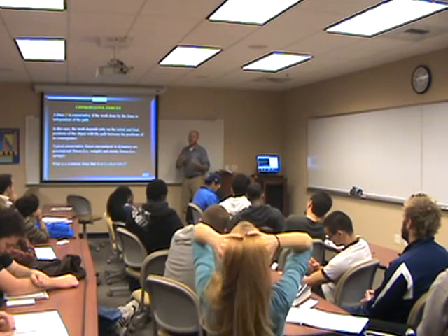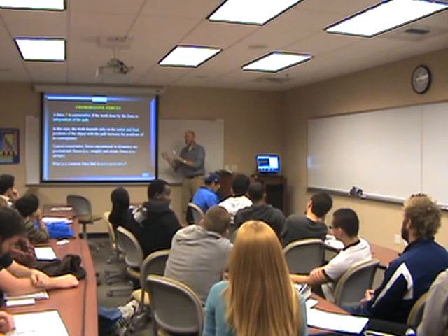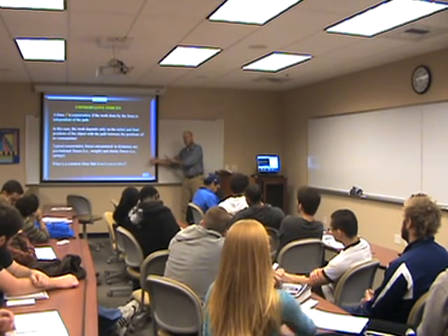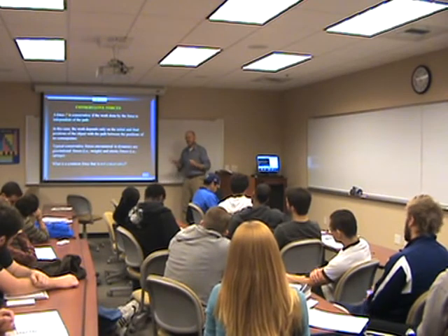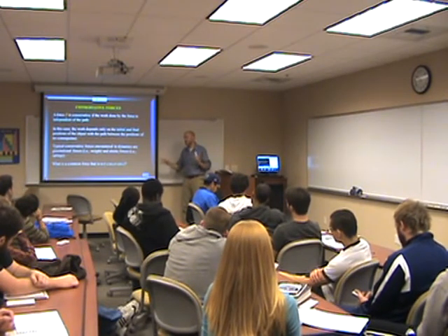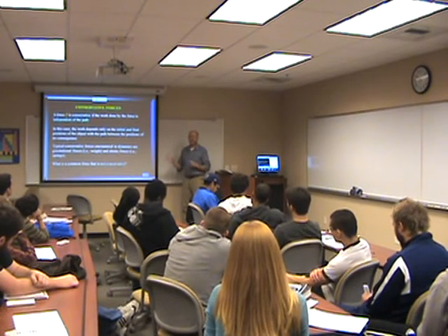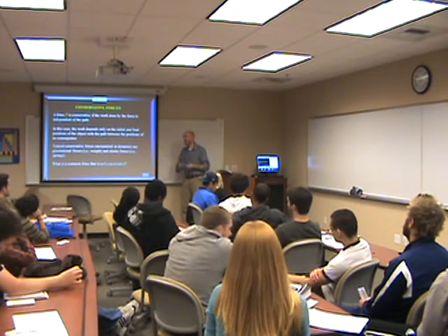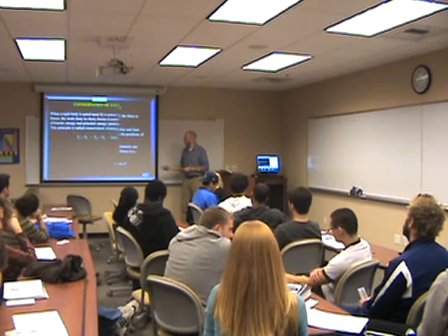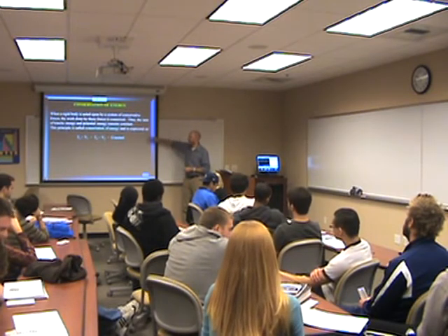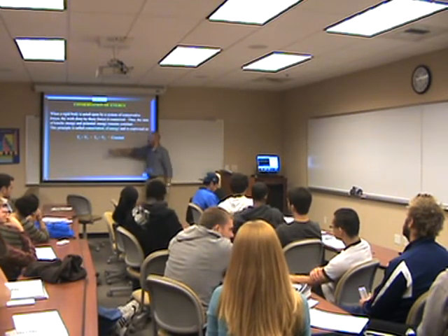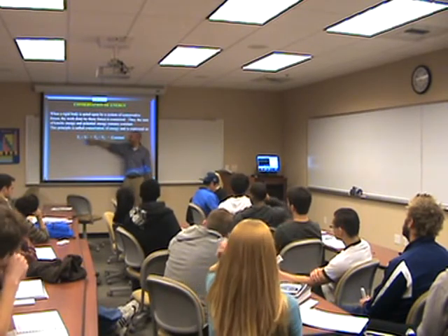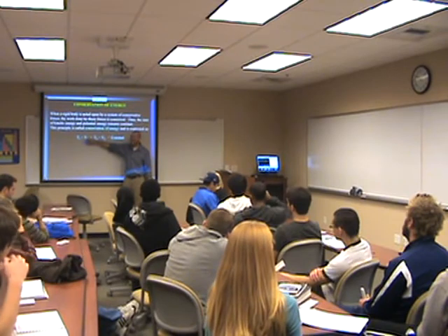You can add that friction force into your work energy. So you can do work energy in terms of potential plus kinetic plus non-conservative work equals potential plus kinetic. And then you can still think in terms of potential energy for springs, so you don't get confused with the work in springs, and you can still deal with your non-conservative friction forces. So if we have no non-conservative work, then we have T, which is kinetic, and V, which is potential.